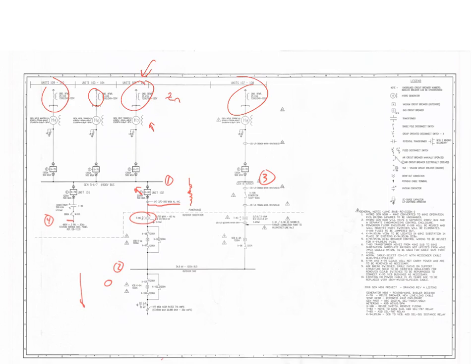If not, well, then you got a problem. Over here, this is Z0 of the generator. It's just going to pass right through because internally in the generator, this is all you have, right? The generator is 3 separate windings that go in and out. They aren't connected until you see this connection right here, which means they're combined together, and then that is actually taken to neutral. All right? So the generator itself looks just like a transmission line, doesn't it? It's actually what happens to the connection downstream is where it makes a change. So the rest of the system is fine.